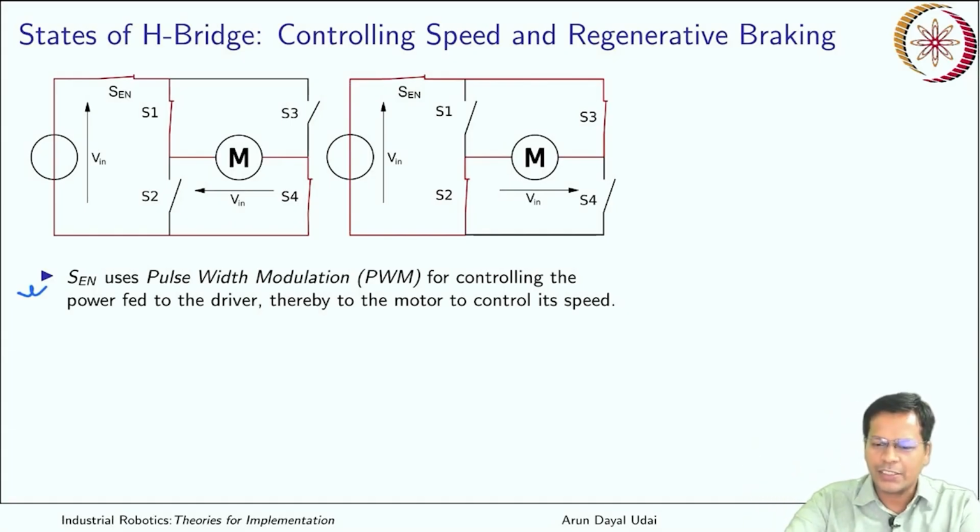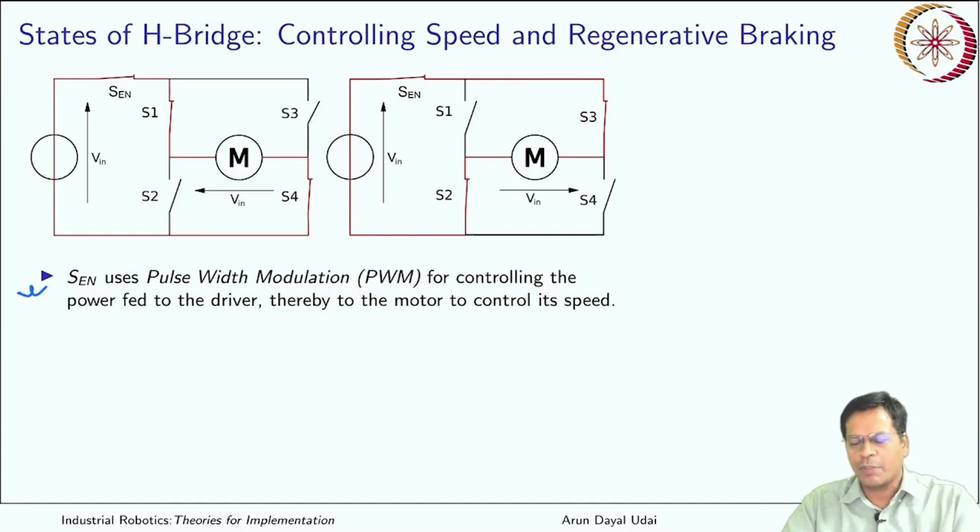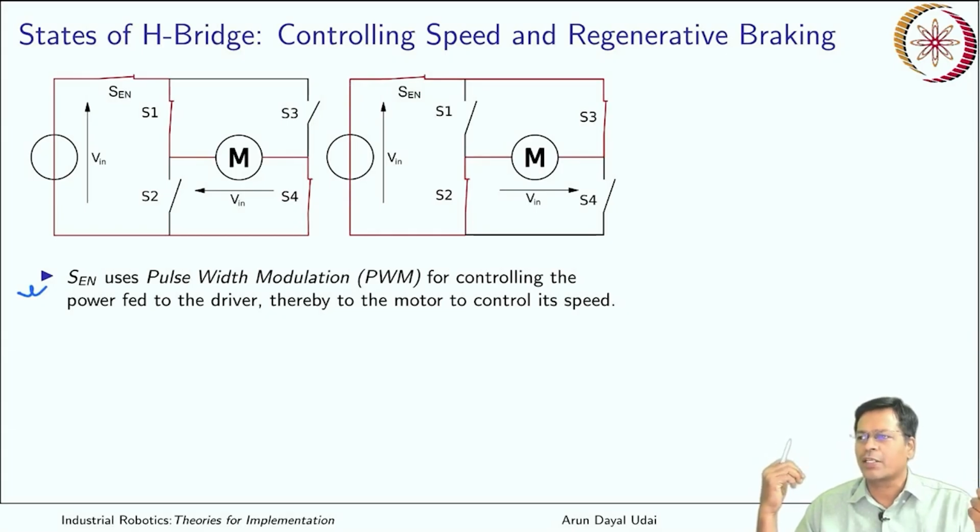But yes, that has a problem. At a very small voltage, the motor may not be running and current keeps on flowing through your coil. If it stays there for a longer period of time, what will happen? It will create a huge thermal load, and finally it can go bad. So that is the reason you should avoid that.